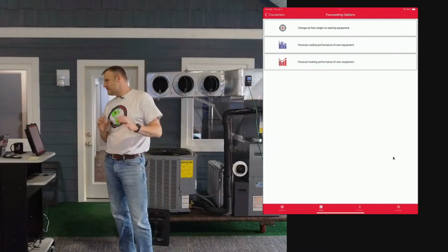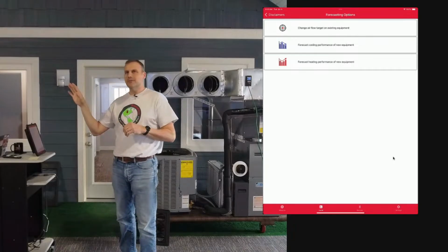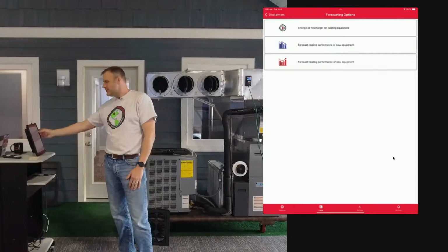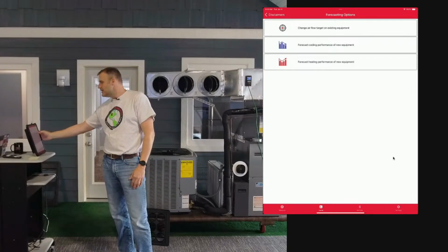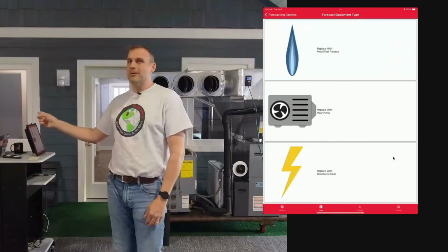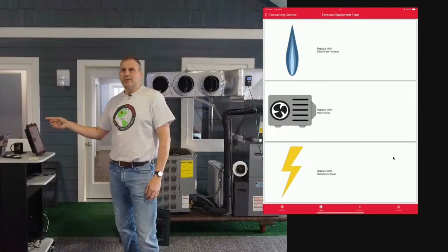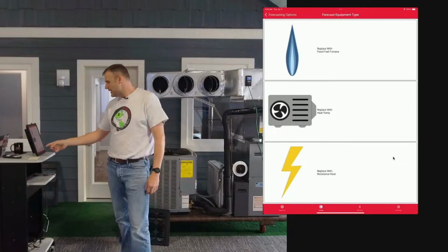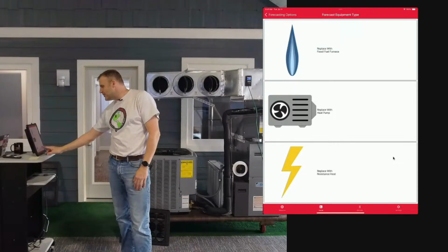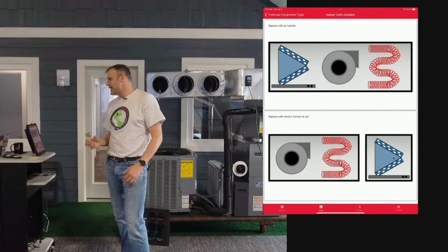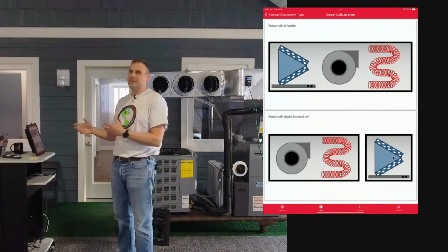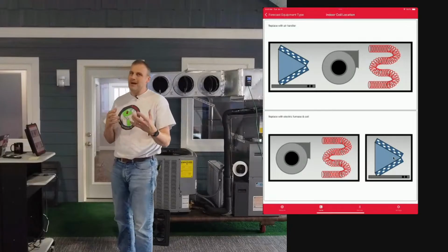So there's quite a few videos out there on the cooling forecast, so I'm not going to jump into that for the essence of time. What I'm going to go into today, which is brand new, is some additions to heating mode. So we're going to forecast heating performance in heating mode, and you'll see that we now have three options. Originally, we had the heat pump, okay? So we've added electric replaced with resistance heat, okay? So I'll quickly jump into that. Resistance heat, we're going to make that selection. We get asked, are you putting back an air handler? Are you putting back an electric furnace with a downstream coil? Those are rare, but they're out there. That's why we asked that question.